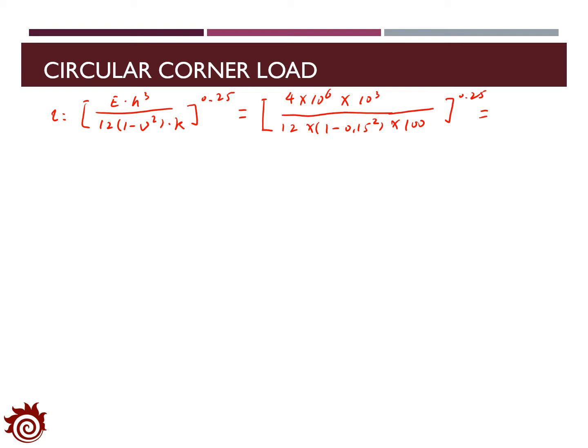With that, we can find out the value of L as 42.97 inches. Then we can find out the value of the stress and the deflection based on Westergaard's equation.